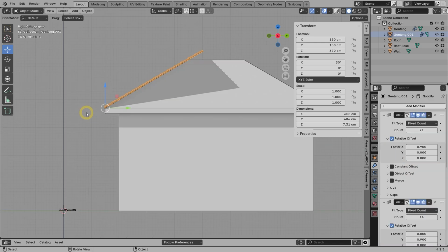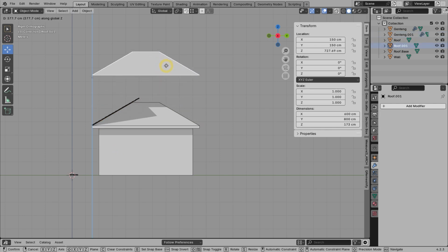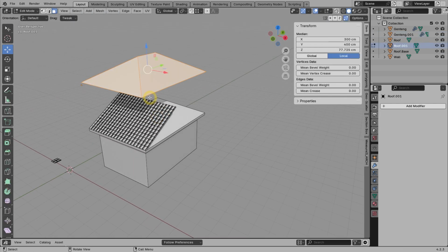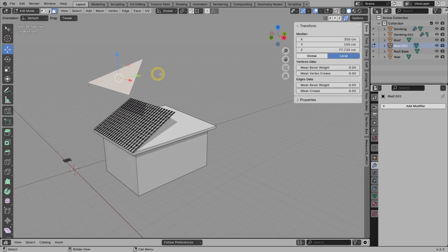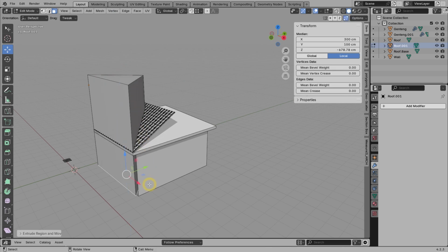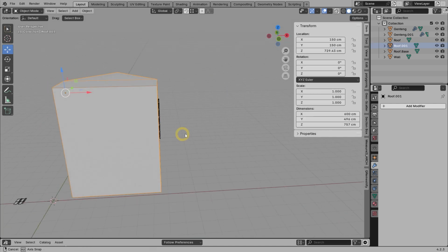To create the operand, we can utilize the existing roof model. First, we duplicate it in the z-axis direction. Then go to face mode and delete all faces except the one directly above the tiles. Next, flatten the face by pressing S, Z, then 0. Then extrude the face downwards. To prevent the front tile from getting cut off, we can add another extrude on the front side. Just in case there are flipped normals, we can select all faces, then press Shift+N. Okay.